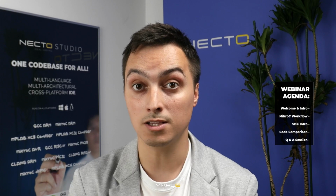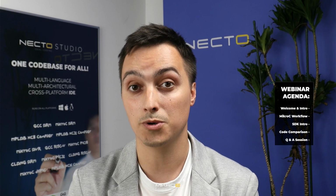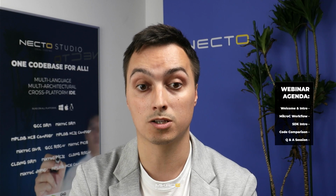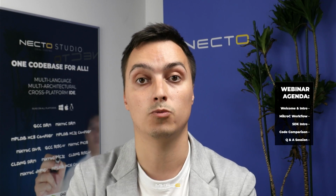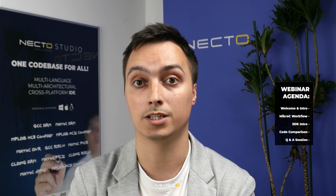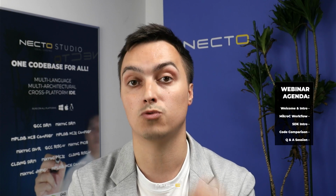Okay, some final notes on the mikroC Pro approach. This kind of code is architecture specific. It is designed for PIC microcontrollers. It is hard-coded to use TRIS and LAT registers, and it is not portable to other MCUs like STM32, AVR or dsPIC. You would need a completely different set of instructions to do the same thing on a non-PIC architecture.